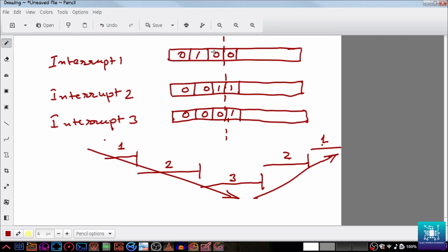It could be anywhere; we are just seeing this scenario. If we only consider the top 3 bits as a group, the group priorities are: here the priority is 1, 0, that is 2, here the priority is 1, and here the priority is 0, with sub priorities of 1, 1 and 0.